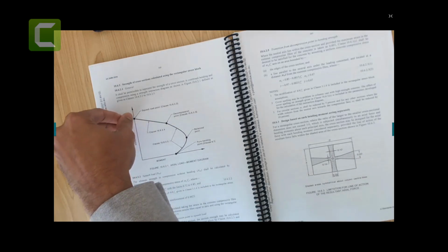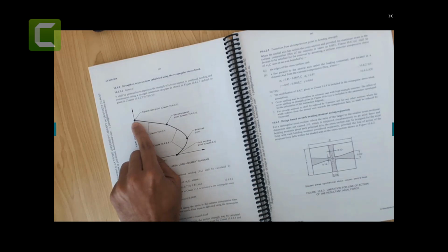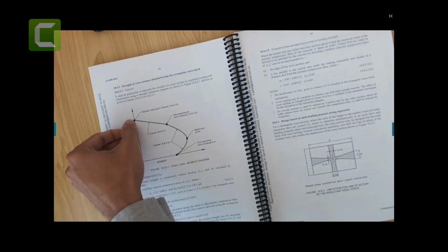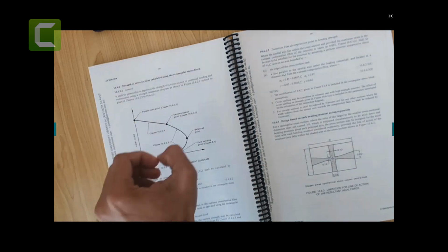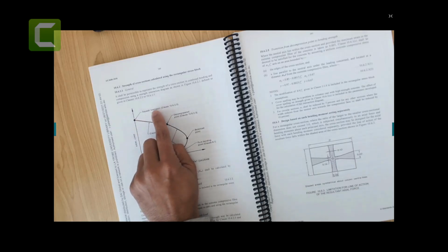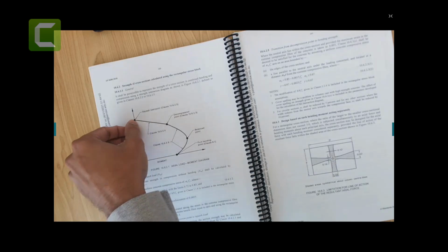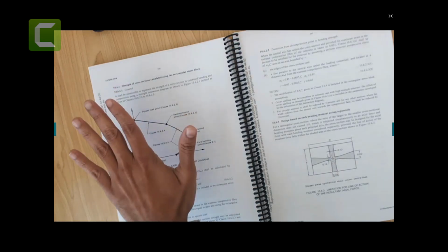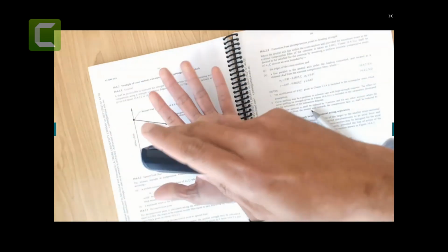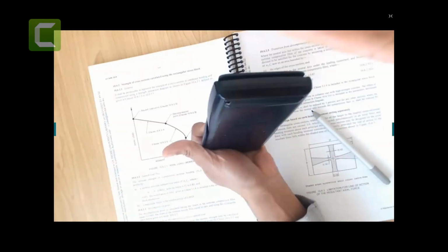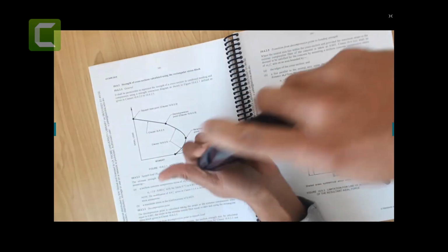What is the easy point? Meaning you don't need to calculate the moment here. Moment is 0 here. You just need to calculate the load, because it is 0 comma load. So the x-axis is 0, the y-axis is the moment. The name of this one is A in our examples, but here they say the squash load point. Squash load point means your column is under pure axial load. If I have a column here with a bottom, and I apply the load here, just like this, there is no bending, nothing else.